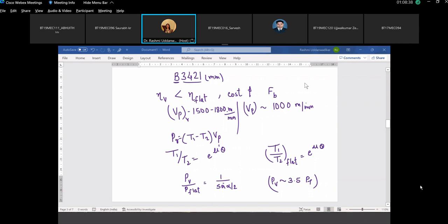What was your point, Saurabh? Define belt efficiency for new or after some revolutions. As you understand, with service and operation, the efficiency will further go down. Normally, the rated efficiency and the rated power are for a new belt, but it is always designed for the worst scenario.